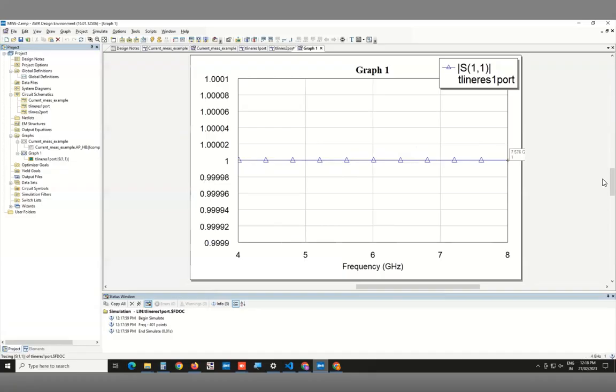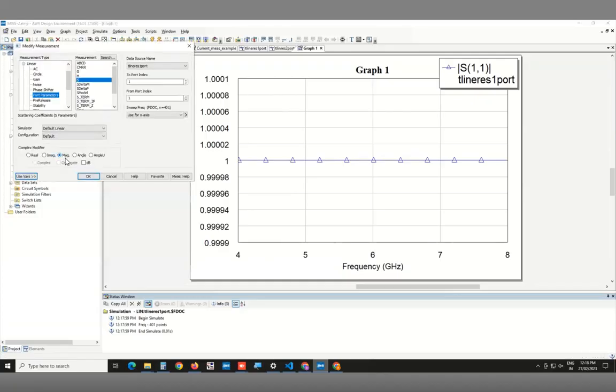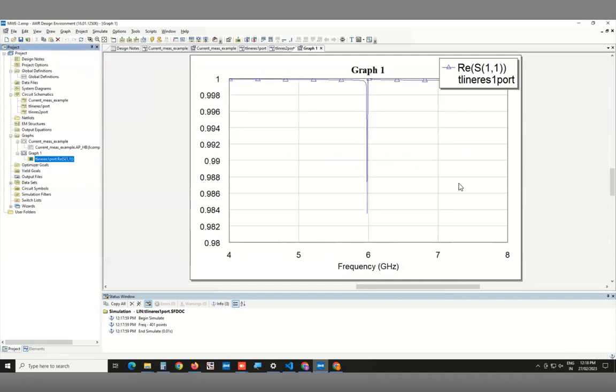You won't see any resonance on the magnitude. We discussed this in class so many times when we looked at the LC resonator. You have to look at the phase or the real part or the imaginary part, right? So let's go to the real part. Okay. So now you're seeing something sharp here. All right. I can imagine that at the beginning of setting up this problem, you might not have had a sense for how sharp this resonance is going to be, and you could have chosen a frequency range which is maybe completely off. But here you see something.